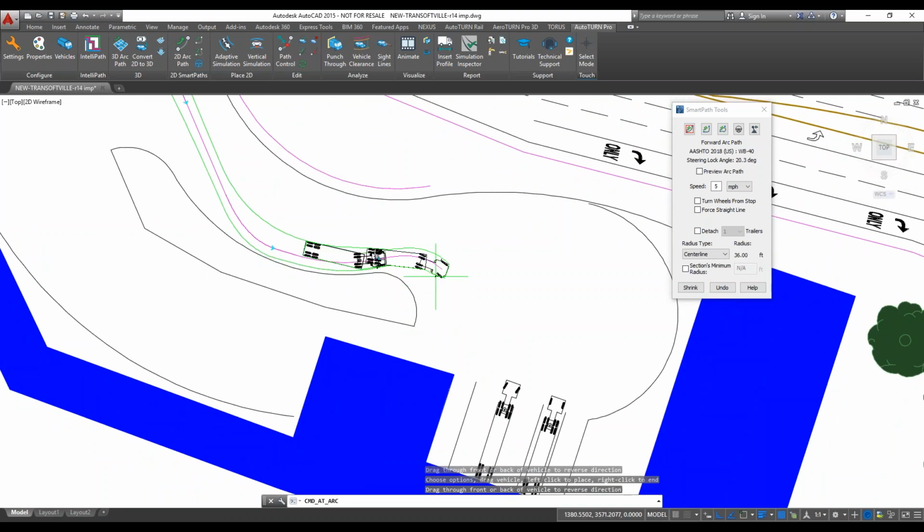I need to use the lock-to-lock time and the steering rate before to generate that transition portion of the path. If I want to turn it on the spot, then I will use the turn wheels and stop option on, and I can change right away. We only recommend this again for this type of scenarios when you need to turn tighter and you're doing low speed.